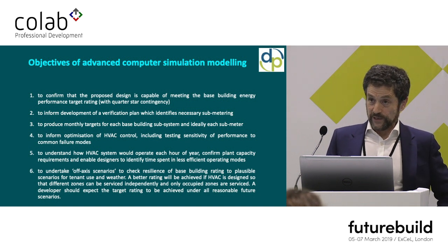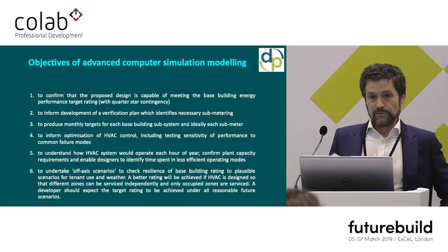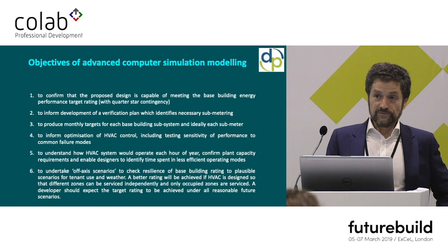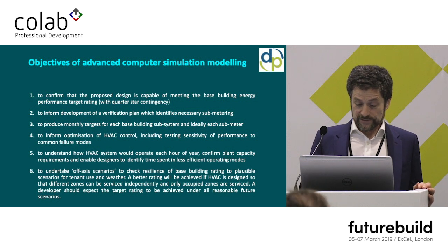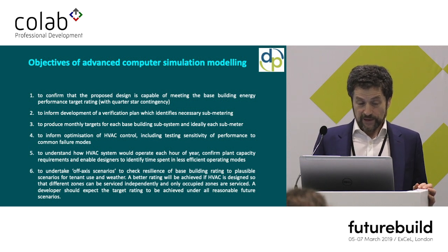You're trying to optimize the control and get it to work in the model, then you can get it to work in the real building. And you're trying to understand whether the plant capacity is appropriate, because the use of advanced modelling can actually lead to cost savings by understanding you don't need as much capacity as most buildings in the UK have, because they just don't test the design under realistic conditions.